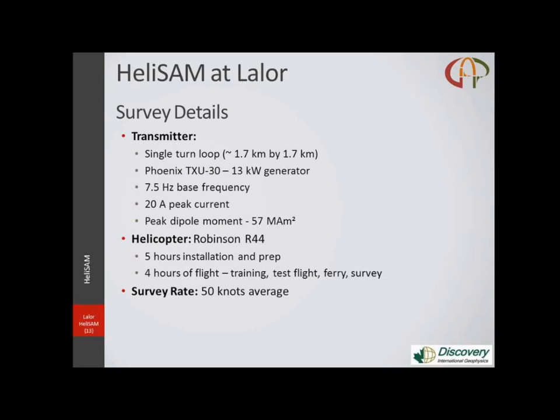The helicopter, it's a light system, so we used an R44, relatively inexpensive and readily available. And the total installation time is about 5 hours and 4 hours of flight. That includes some training, some frequency test flights. The survey itself only took a couple hours. And the average survey speed was just under 100 kilometers per hour.